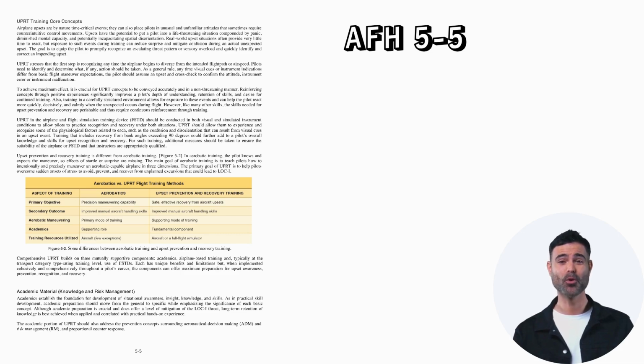As a general rule, anytime visual cues or instrument indications differ from basic flight maneuver expectations, the pilot should assume an upset and cross-check to confirm the attitude, instrument error, or instrument malfunction.